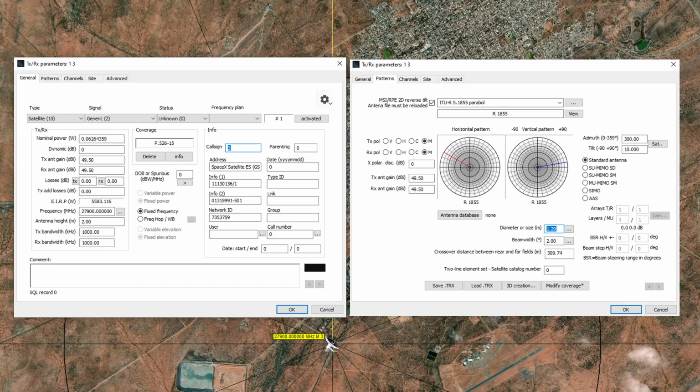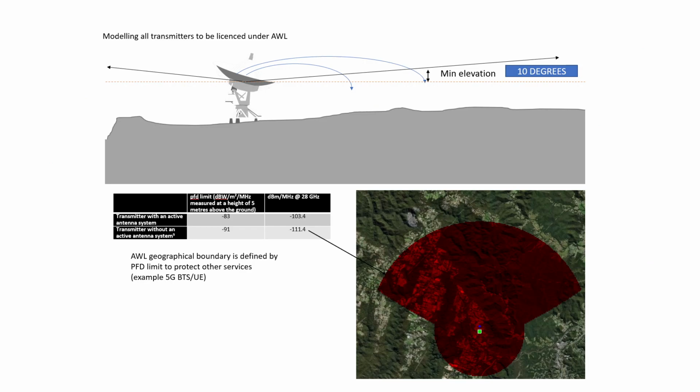These are the technical parameters. We define transmission power per megahertz, antenna gain, frequency, antenna height, and we have the antenna pattern following ITU, and we've got the tilt or the azimuth information, but obviously there will be tracking involved here. Here the simulation is based on an Earth station transmitter with variable elevation and azimuth orientation, because like we said, it's NGSO. So the tool is going to vary the antenna orientation and compute the emissions for all possible combinations.